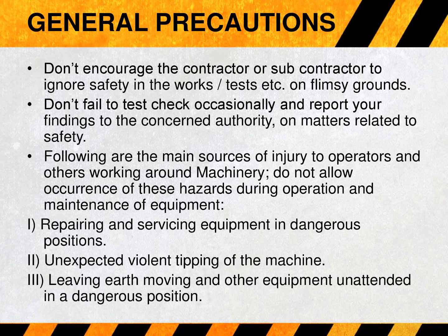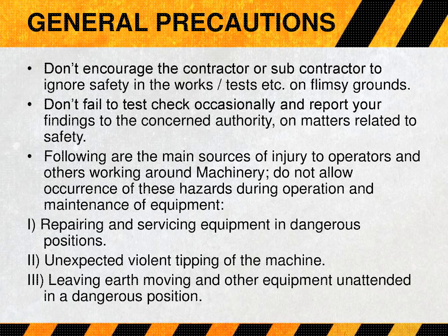Following are the main sources of injury to operators and others working around machinery. Do not allow occurrence of these hazards during operation and maintenance of equipment. 1. Repairing and servicing equipment in dangerous positions. 2. Unexpected violent tipping of the machine. 3. Leaving earth moving and other equipment unattended in a dangerous position.